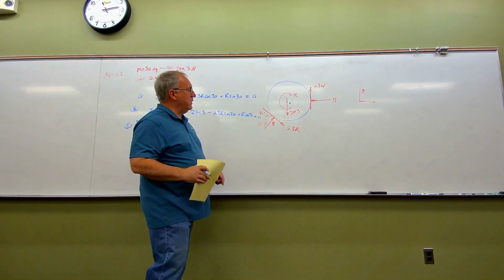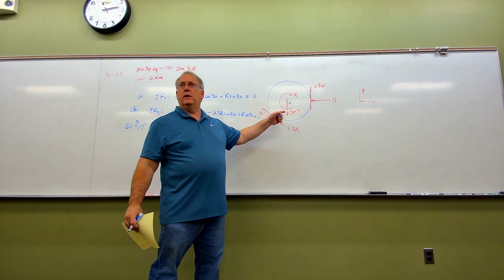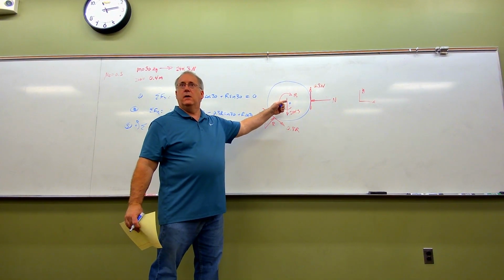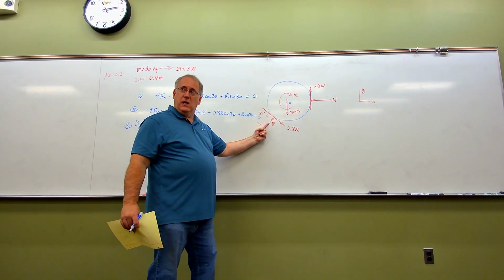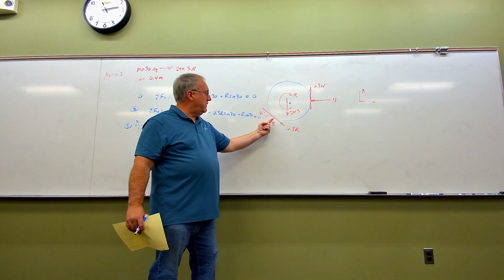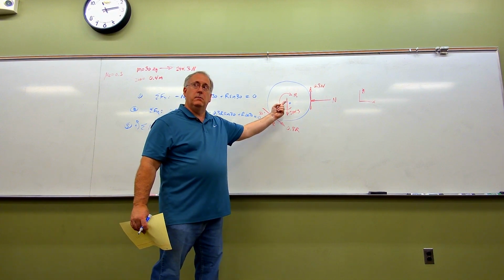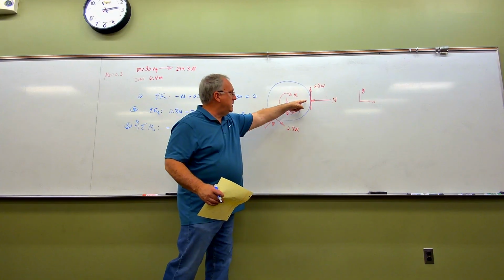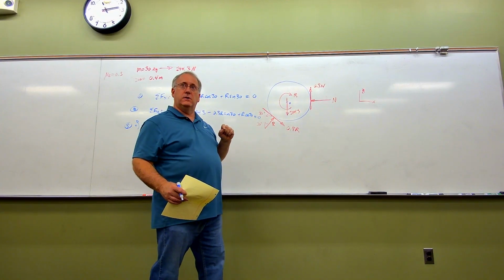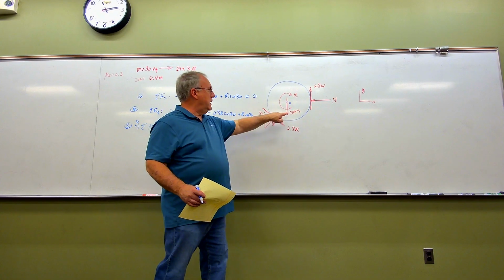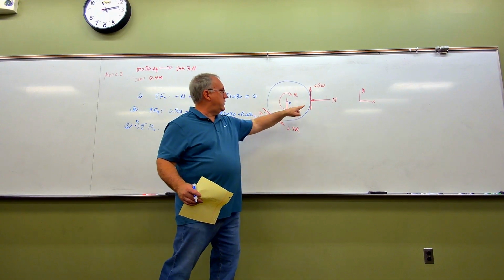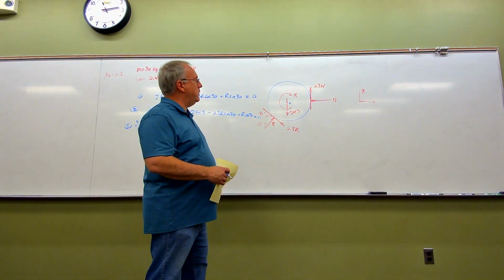And then very importantly, the 294.3 goes right through the moment center. But so does the normal force here. The line of action of R passes right through the moment center, and the line of action of N passes right through the moment center. So they're not in play. So nothing due to this, nothing due to that, nothing due to that, but I've got that 0.3N right there.